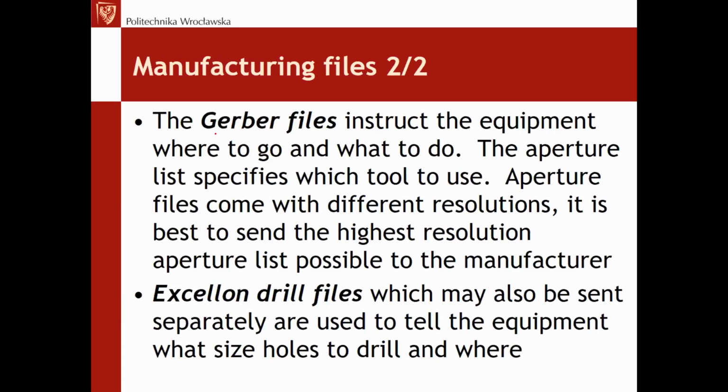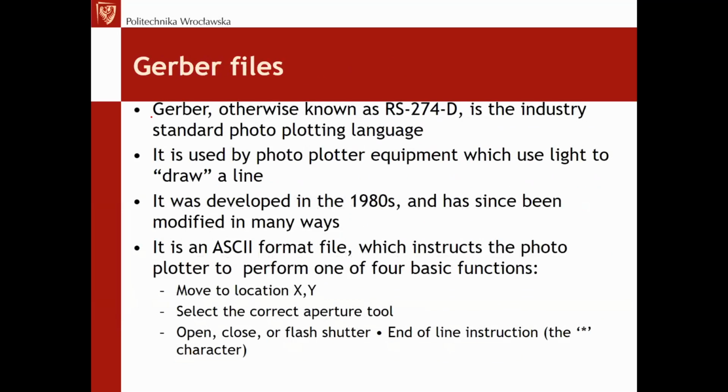What are the Gerber files? Each layer is described in the Gerber files. However many layers we have, even the mechanical layers are generated. A Gerber vector file is generated for each layer. In general, they instruct the equipment where to go and what to do, and with what instrument, because that's for a plotter, which is what the Gerber file is.